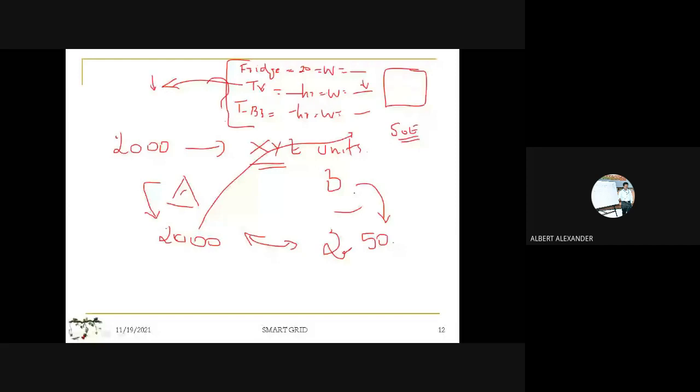Or you will see that, out of all the tube lights, one tube light is consuming a larger amount of energy. That may be because of your mechanical choke, or because the conductor may be damaged, or due to a difference in the reactive power. So based upon that, this tube light will give a different set of readings.